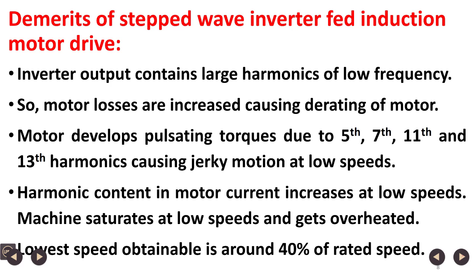Because of this, each harmonic voltage will contribute to harmonic current, and due to that there will be harmonic I square R losses in the windings, and also increased core losses due to harmonics. So motor losses are increased, causing derating of the motor. Motor rating reduces, output reduces.